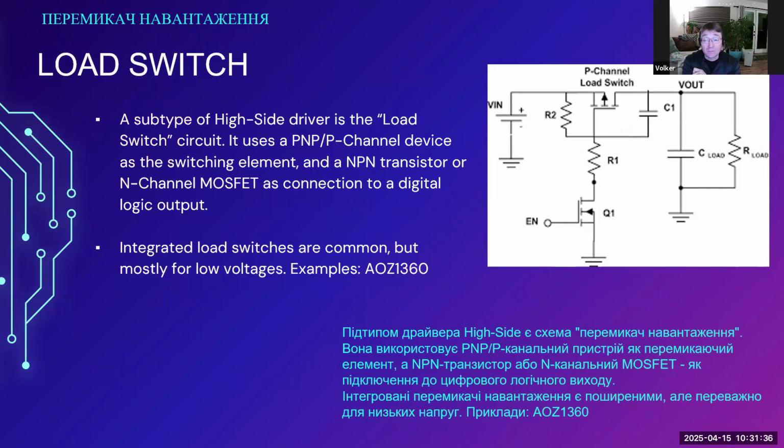And depending on the values for R1 and R2, the turnoff might be very slow, too slow to be used for PWM. So this type of circuit can be used for slow PWM, up to a few kilohertz, but more generally, it is used for permanently turning a device on or off.